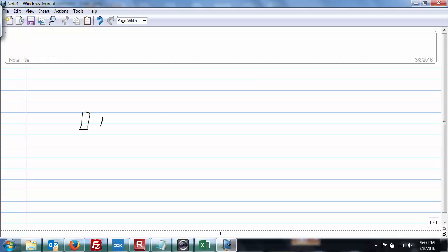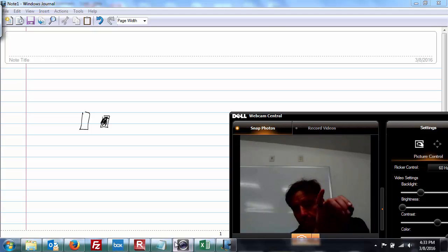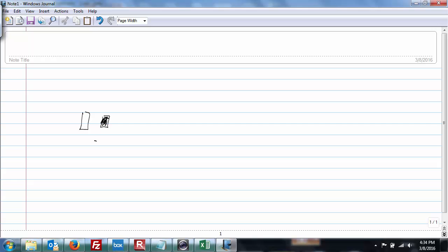What you're always going to see is the hot one is going to be your black, and it's smaller because it's harder to get your finger in there. That's the one that's going to shock you, right? And then your ground is down here. There were no ground wires in Japan either, only 2 prongs. How do they do that? I don't know. Okay, but this is going to be a 15 amp circuit.